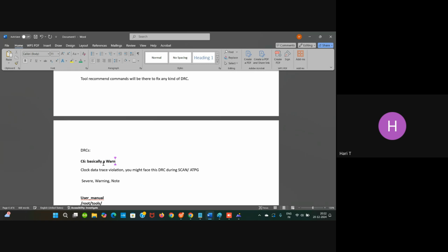Sorry, I said it is severe. Sorry, it was an error. DRCs are 3 types: one is error, another is warning, another is note. You can always ignore a note. Please do note, a note is a type of DRC you can ignore.